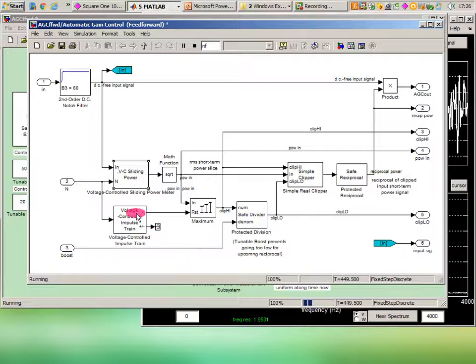Well, every n samples, I reset this running maximum calculation. Because I have no idea how big is big and how small is small inside my waveform, I have to interrogate it with this block right here. And so over 50 samples, I found out who's the biggest in that block of data. And then using the factor 20, let's say, it's easier to understand this boost, I take 1/20th of that maximum and let that be the low clipping level.